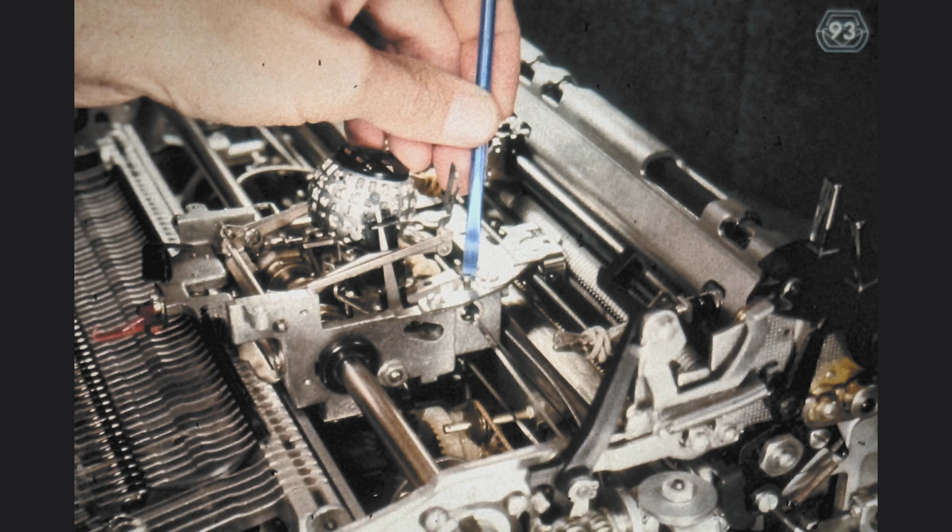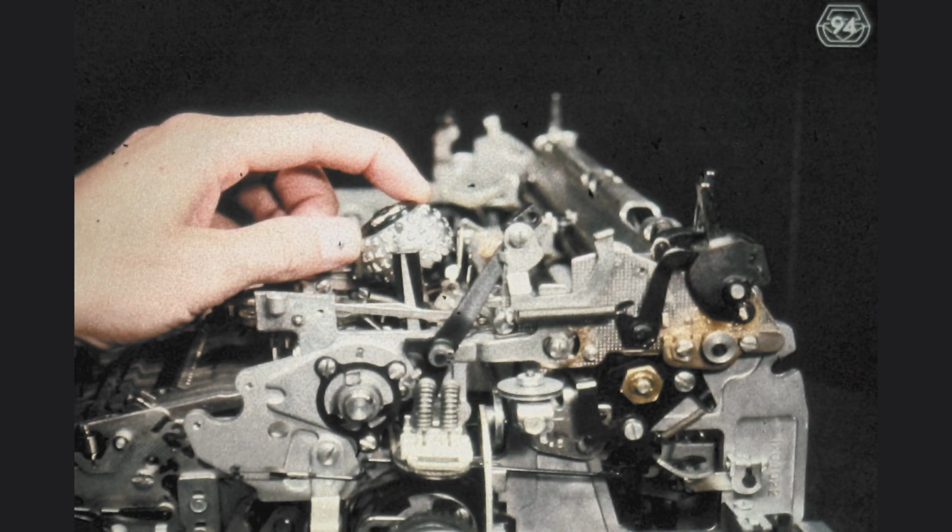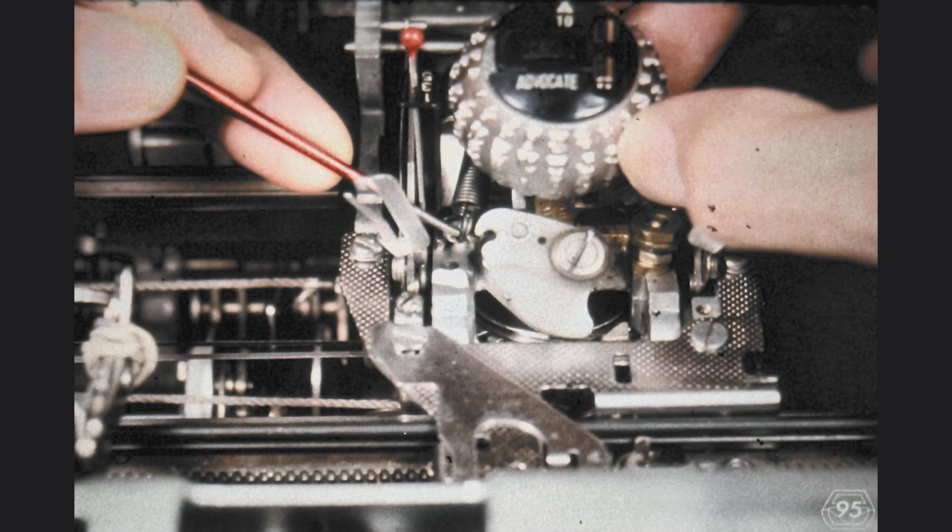If at this point you do not yet have the tilt tape around its pulleys, don't let it worry you, simply continue. In order to obtain maximum slack for the tilt tape, we tilt the type element all the way toward the front. It then becomes quite easy to install the tilt tape around the left and right tilt pulleys. Our last step in reinstalling the tilt tape is hooking up the tilt spring. Had this been a repair job, we would now be ready to adjust the tilt mechanism.